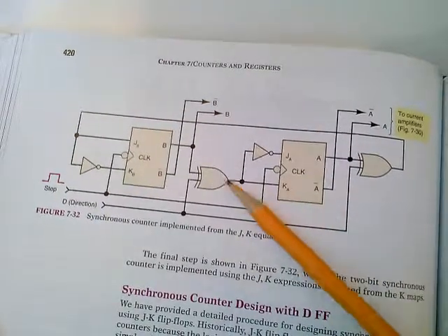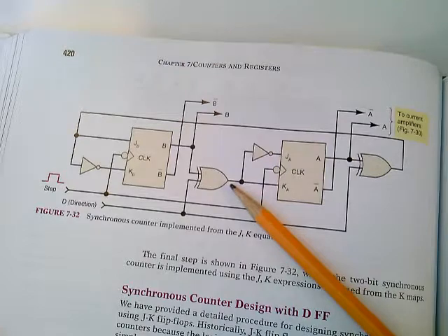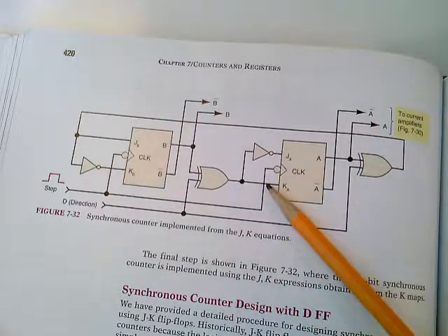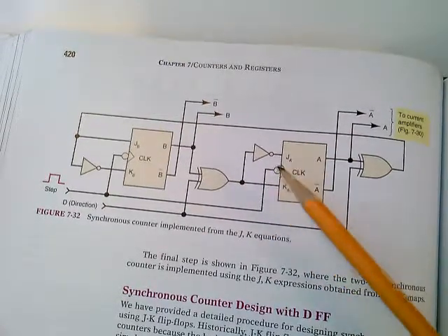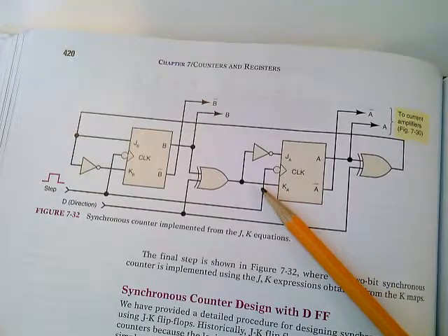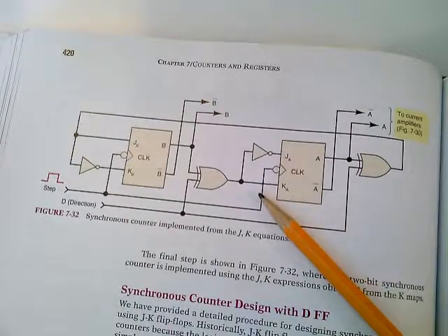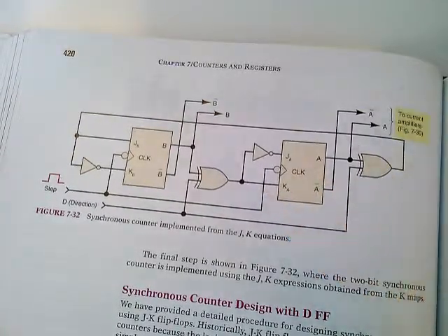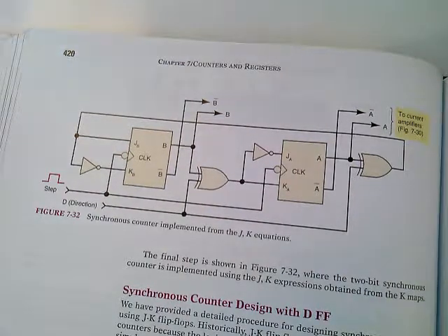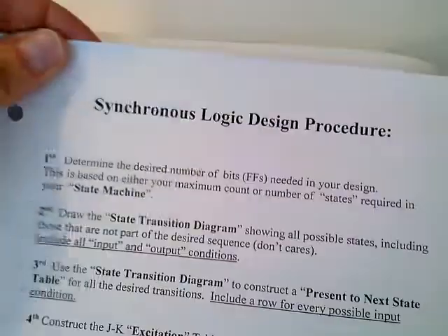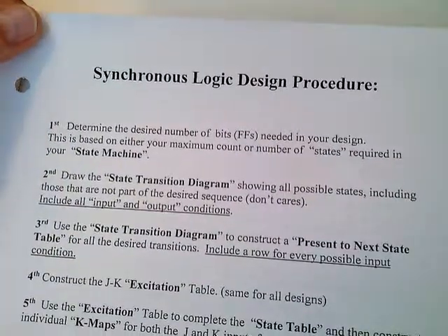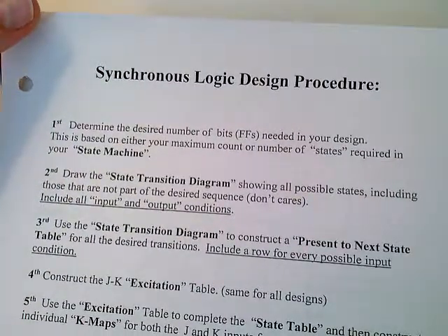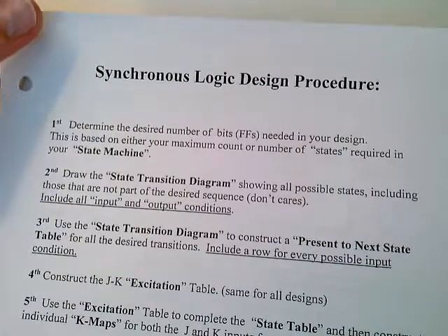This particular circuit will rotate that stepper motor in 90-degree increments. Not very granular, but you can see how we used the synchronous logic design procedure to design this synchronous controller. In this case, the stepper motor controller.